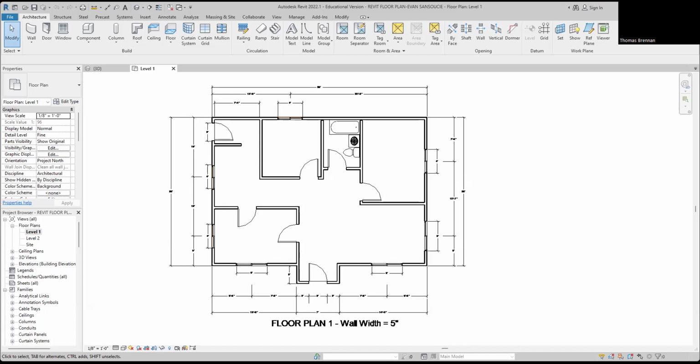Make sense, Casey? Okay, now let's take a look at another one here. This is 46 feet. So I'm going to take my 1/4 inch scale, take it right here and put it right to there. When I bring it right to there, it comes right up to 46. So it goes all the way from 0 to 46. Now over here, just to pick up something a little different, we'll do this 36'5". The 36'5" dimension starts at this hash mark right here and goes over here.